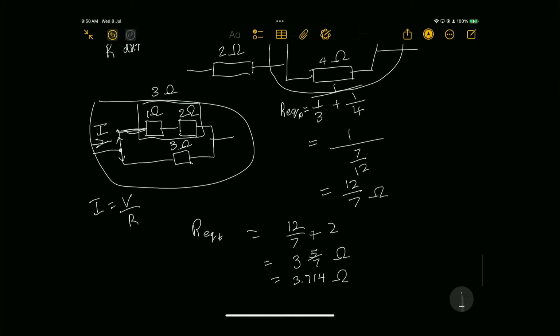So we could draw that. Well, actually, we don't need to draw it. We see it here in the same diagram, with the same explanation as I was given before, right? The amount of current I that is going into this junction in this circuit is equal to, let's say, I1 goes upwards and I2 goes downwards, right? So then Kirchhoff's law states that I is equal to I1 plus I2. Right, that's what Kirchhoff's law says.